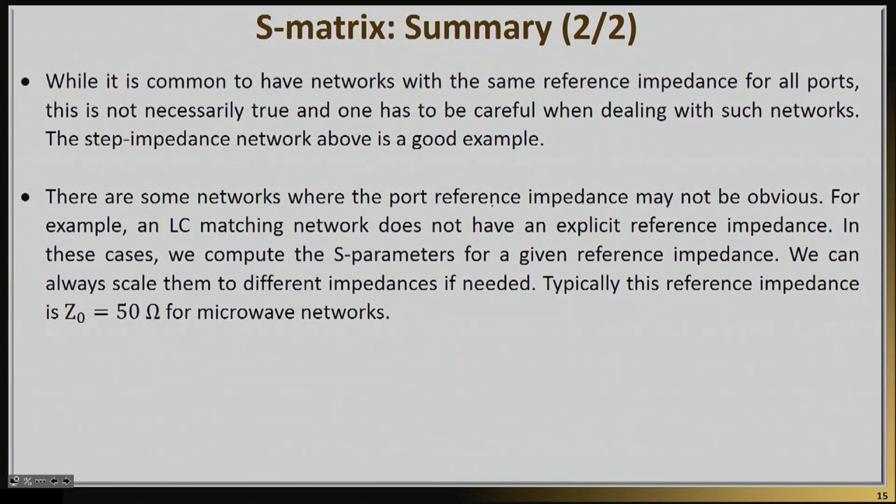Finally, the S matrix may give you some trouble if you don't know exactly what the characteristic impedance is, particularly in cases where you work with lumped elements. In that case, you should be using the reference impedance of the entire system that you're designing, and there are easy ways that you can rescale the S parameters for different reference impedances. We will see that in a future lecture.